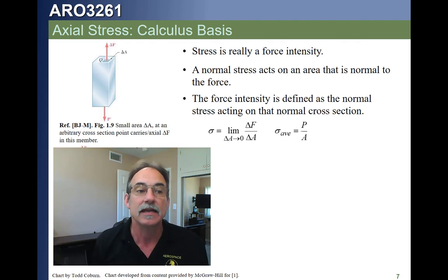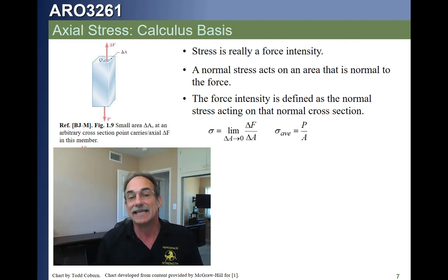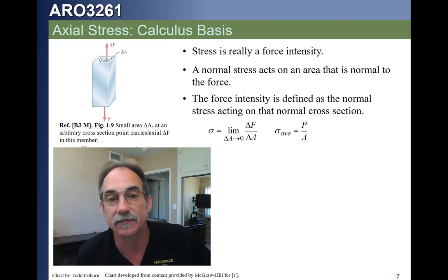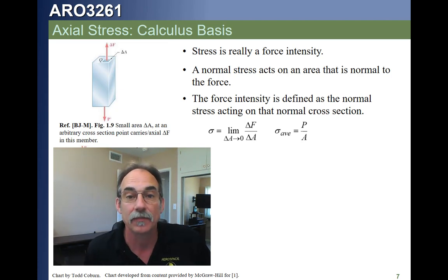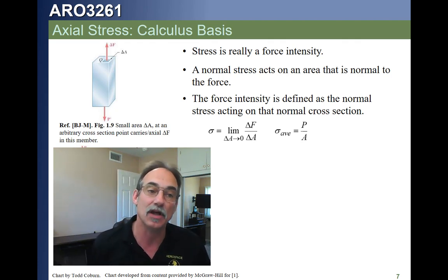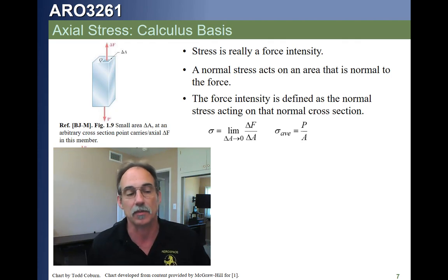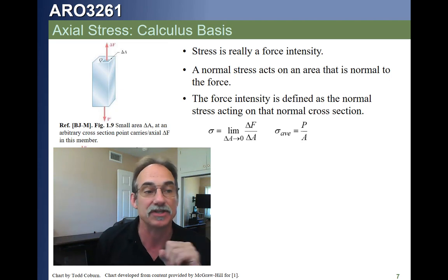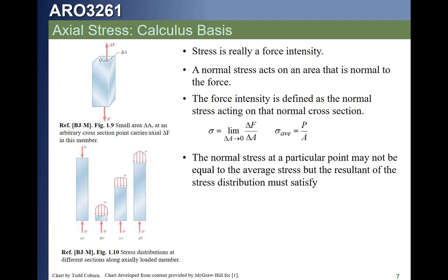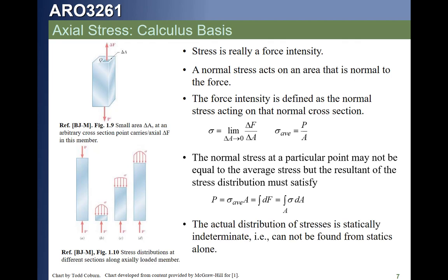Now there are times when we use this calculus to calculate the stress, but most of the time we're just going to take P over A. What we will do is go back to the calculus as we look at different kinds of loadings and what effects they have on the structure. But we're often going to come up with a simple equation like P over A to figure out what the stress is. Since the stress is defined in this manner, we can calculate the force by just taking the integral of the stress with respect to A. Okay?